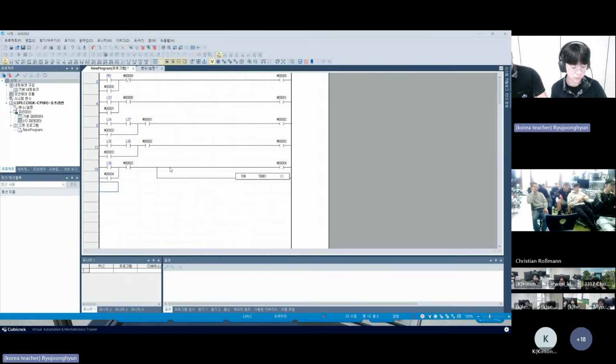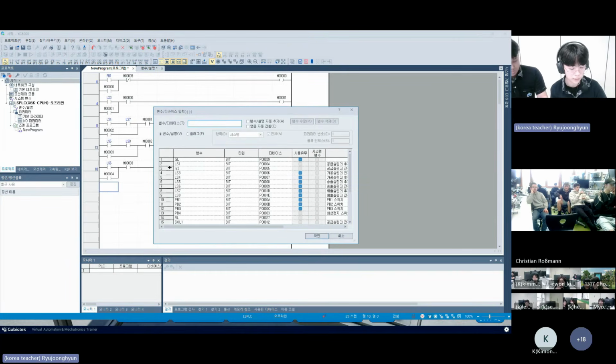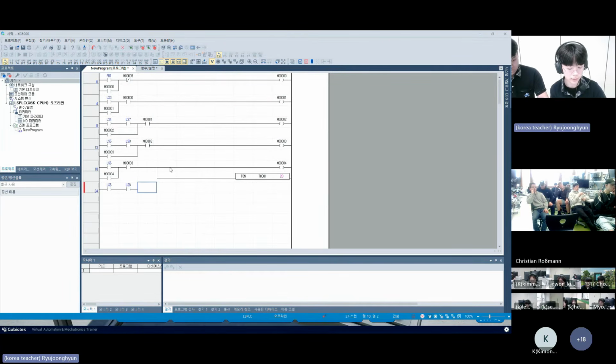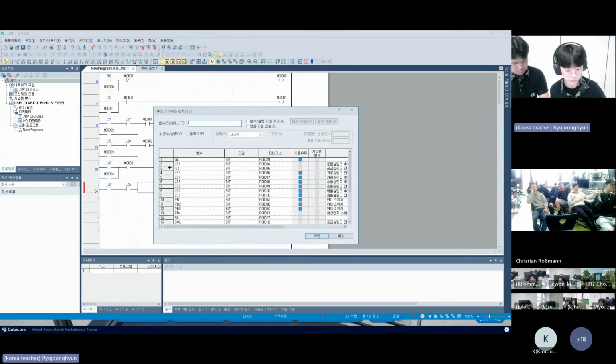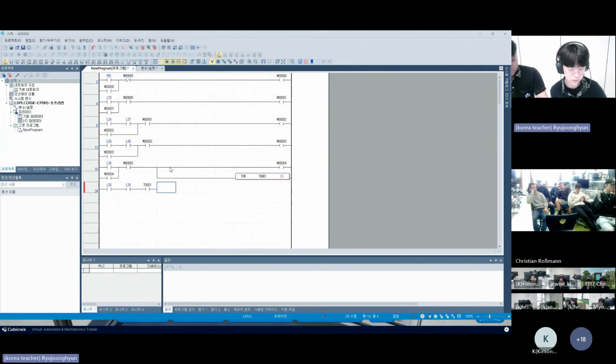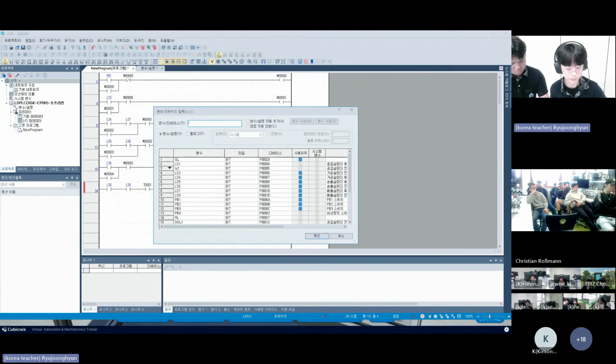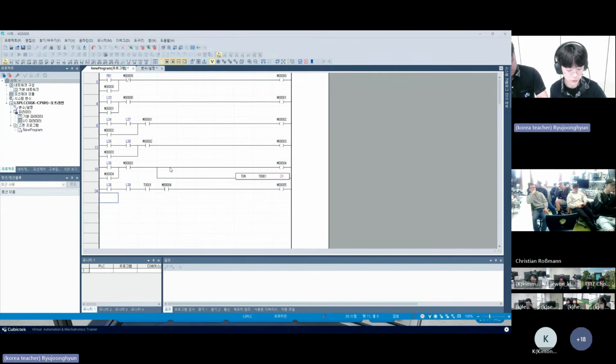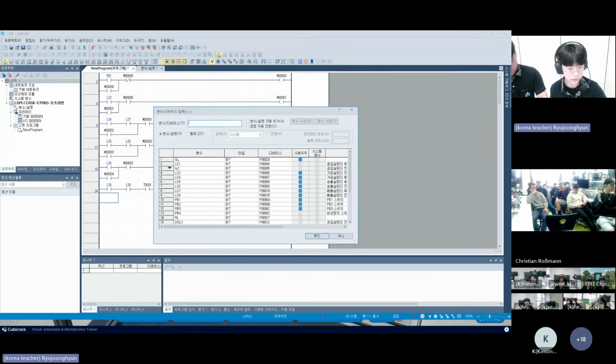In M5, the forward cylinder moves forward, activating limit switch 6, and the eject cylinder moves forward, which is indicated by limit switch 8. Timer T1 is added to prevent M5 from receiving a signal during the 2-second pause in M4. M4 is also used to ensure that M5 does not activate before the preceding action. M5 is used for both the coil and the self-holding circuit.